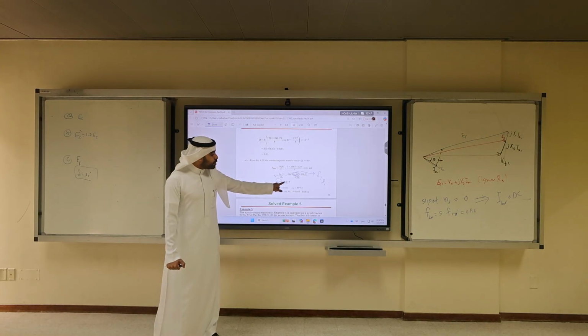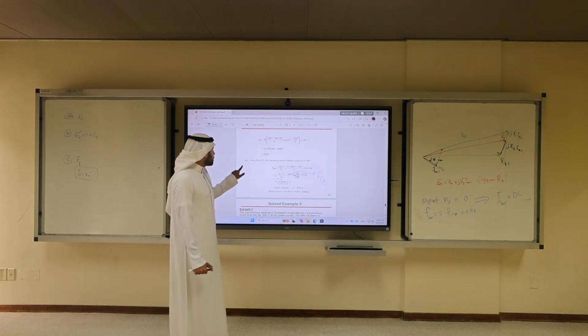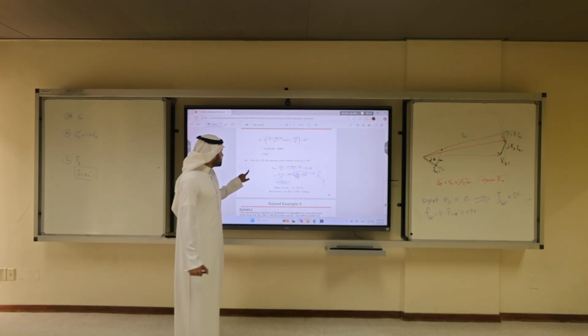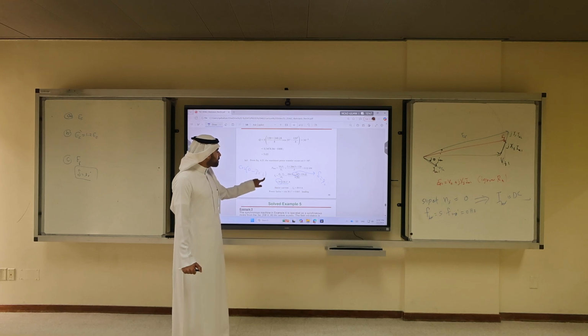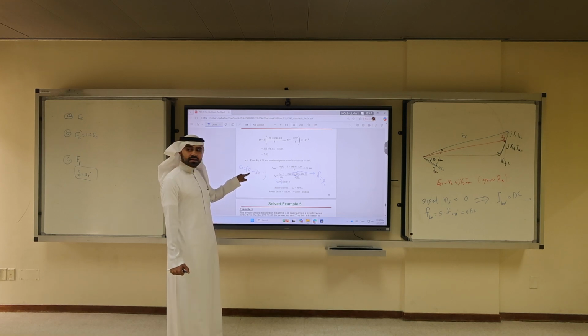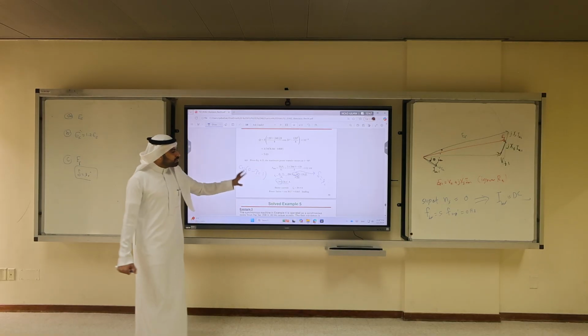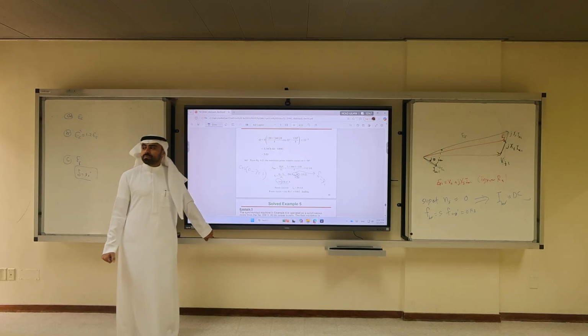And what is the angle of the power factor? Only 30 degrees. So the power factor dropped to 0.865 and it became leading. Why? Because we have cosine of, what's the angle of terminal voltage? 0 minus, what's the angle of the current? 31.5. So the current is leading the voltage, so this is leading. So this is the operating condition at the maximum power transfer.